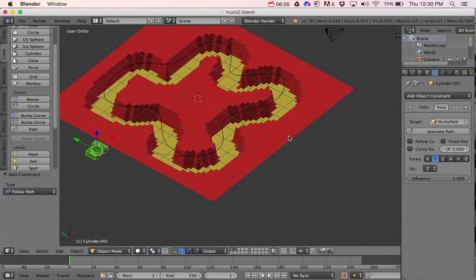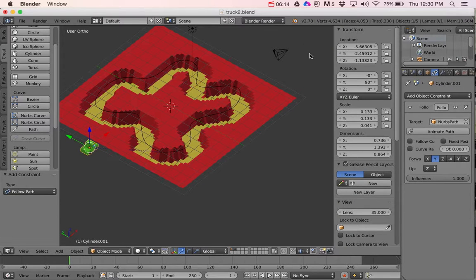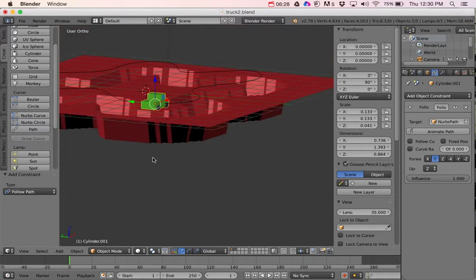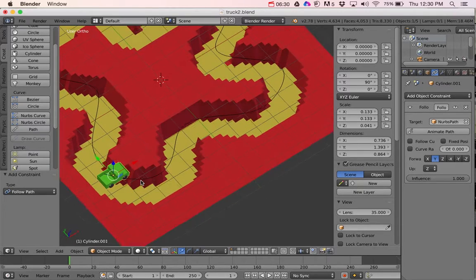It's like all the way over here. So don't worry about that. What you need to do is zero out that vehicle. So I'm going to click on that little plus, or you can press the letter N on your keyboard. And on location, I'm just going to do 0 tab, 0 tab, 0 tab. So that should get it on there. And don't worry about it being not on the ground yet. We can fix that later too.